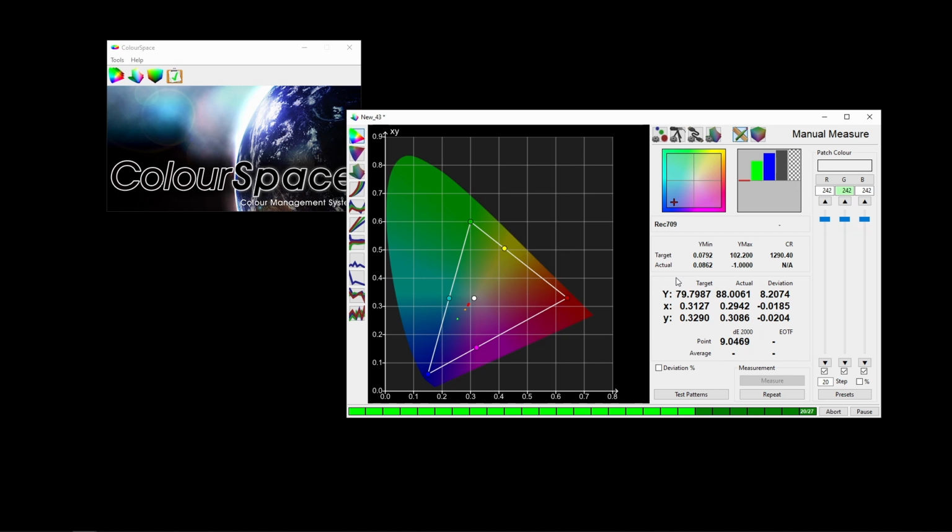And now it's getting through the grayscale, and it's giving 109 when it's expecting 102. That's the reason there's the target from before. And you can see now there's the red down here. So the red on the CG319 is basically a DCI-P3 red, which allows you to get that calibration with DCI-P3, very good.